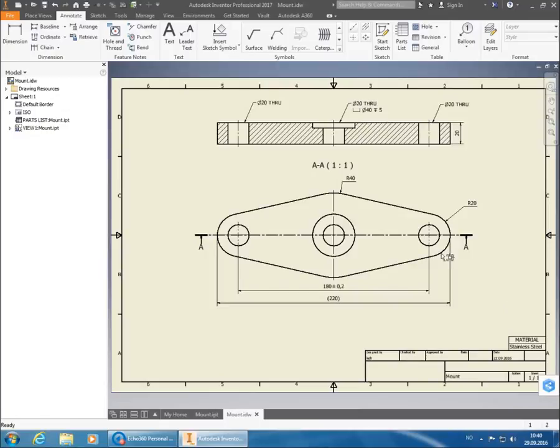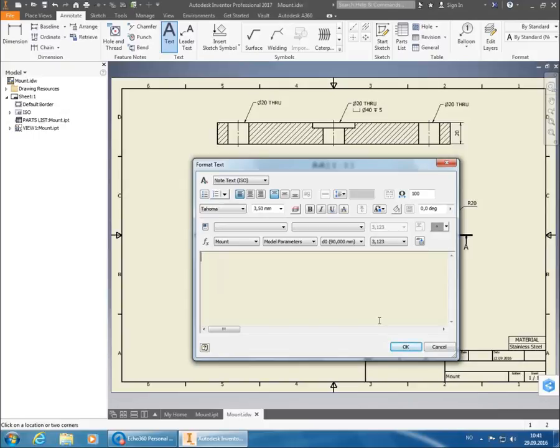Then we're going to do general notes, general tolerances, and notes afterwards. We need to use the text function up here. Just place it somewhere in the vicinity of where we're going to have it to begin with, until we see how much space the text is going to take. General tolerances and surface finish. We have the ISO 2768-1. And in this case, I had set medium. And then we have ISO 2768-2. And it was set to K, capital K, which is the equivalent of medium.